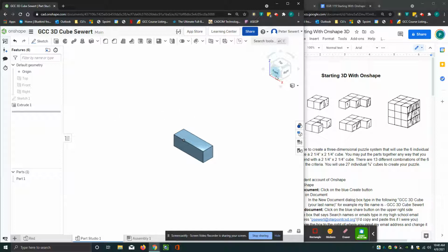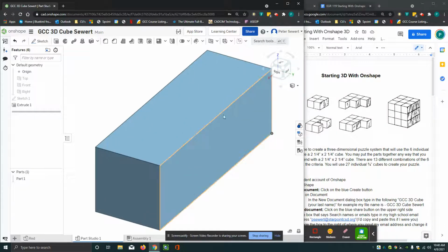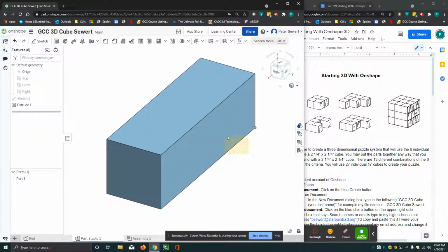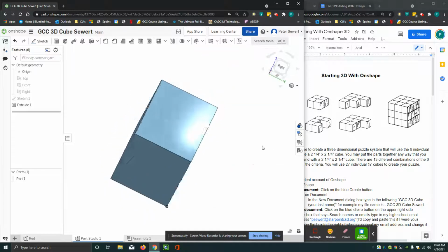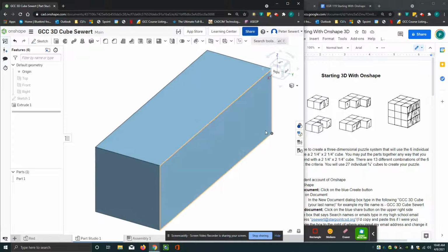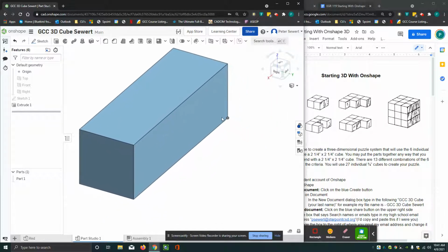Now what I've got to do is add these two little blocks on the top of my part, and I'm going to want them over here behind this long cube. So I'm going to spin this one time, and I'll zoom out. By the way, you can click on this and spin these things. Middle mouse button's pan. Right mouse button allows you to spin things around, and then you can of course just click on the view cube's corners to get things back to normal.